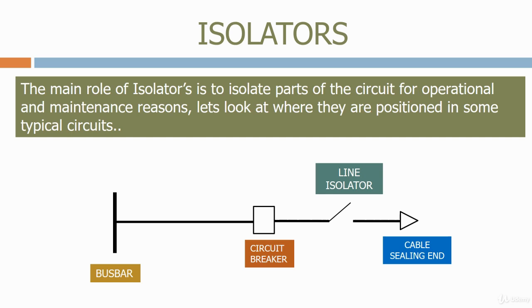Similarly, when we're maintaining the circuit breaker, we need to know that there's no possibility of electricity flowing into it from the bus bar. For this reason, we normally provide a bus bar isolator. This also provides isolation from all the other circuits when we want to work on or maintain the bus bar.